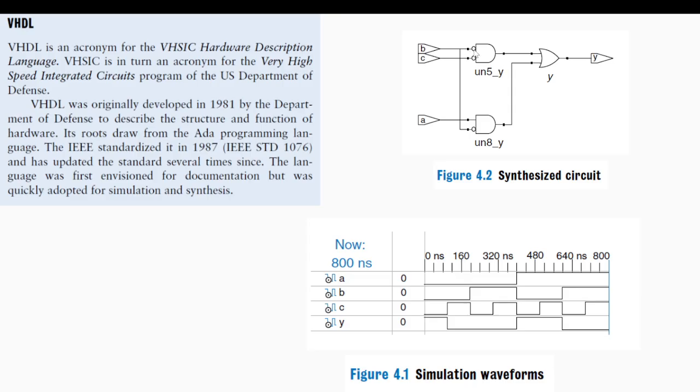If the AND IC has that feature, then only two ICs are required. But if we can only find a simple AND IC with no inversion, then we need an inverter, so we need 3 ICs. Then for prototyping we use the breadboard, the wires, power up the circuit, and make sure that we are getting these timing diagrams.